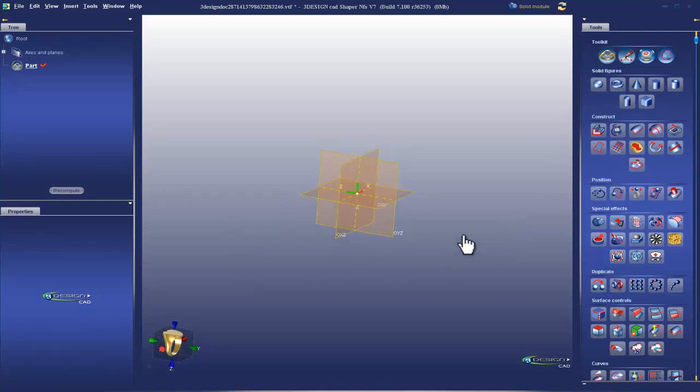The other most important function is called panning. Panning is moving the workspace from side to side or up and down on the screen. You can achieve this in one of two ways. I do it by holding down the track wheel like it's a button and simultaneously holding down the right mouse button. This is a little tricky to do on some mice.